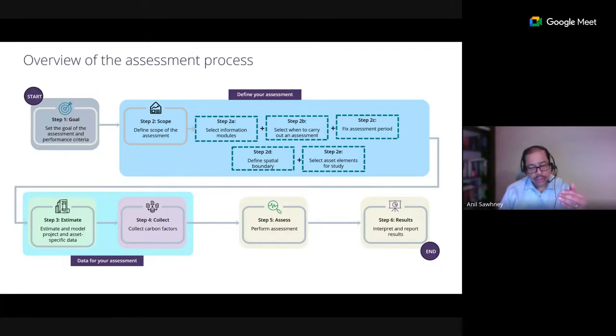You also need to estimate your energy use and your water use. So you typically would run an energy model, which we are now very used to. For decades, we have done energy efficiency. Most projects have. If you're getting either a GRIHA or a LEED certification, you would do your energy model. So that estimate is also needed. That is your step 3.